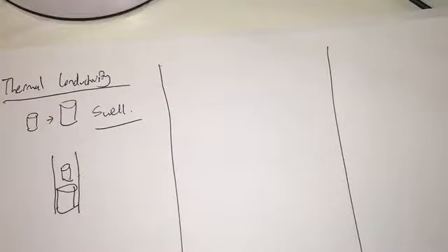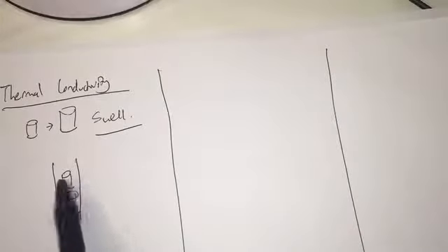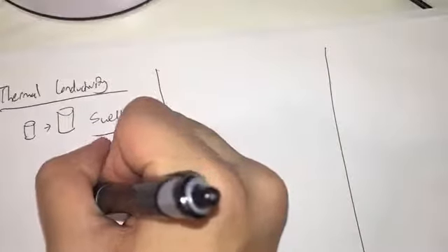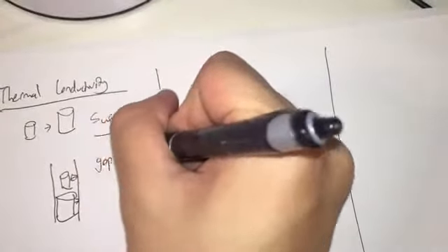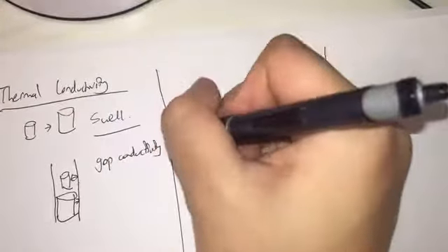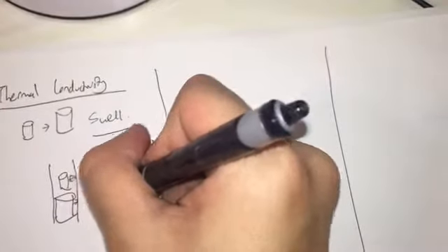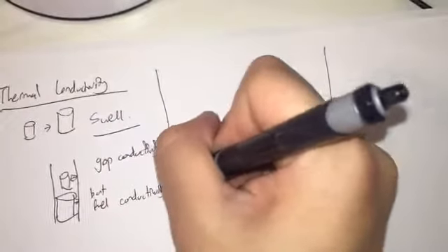But within the fuel itself, because this was completely solid and this is now a mixture of solid and gases, the conductivity actually decreases. So the gap conductivity increases because the gap has been decreasing because of the swelling, but fuel conductivity decreases.